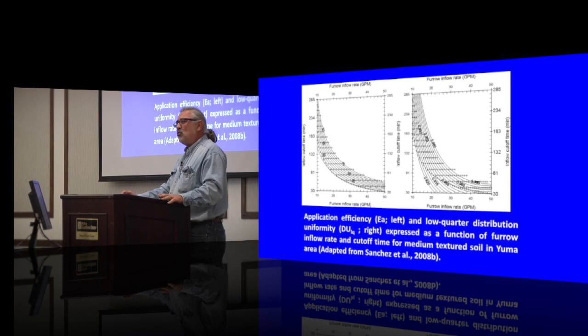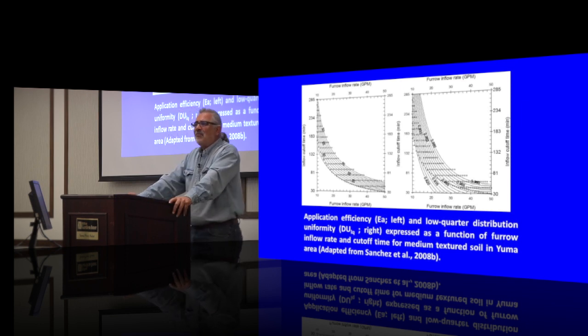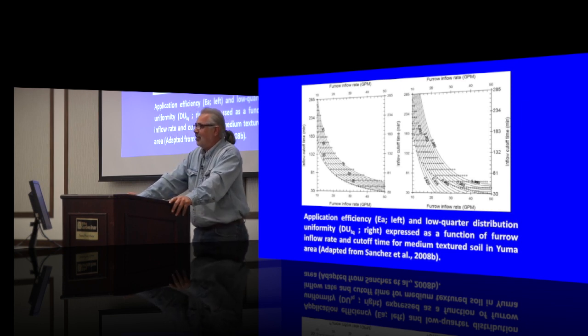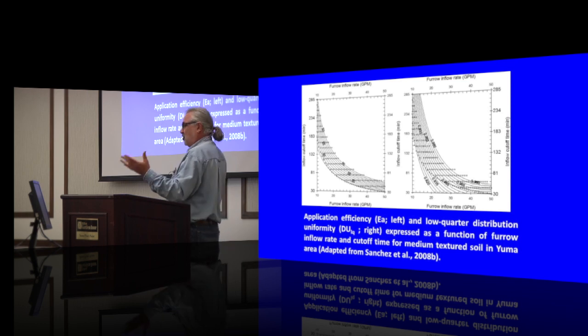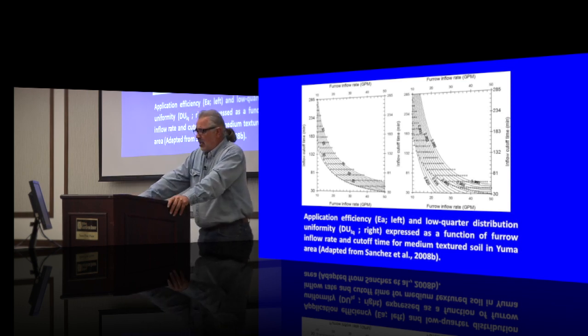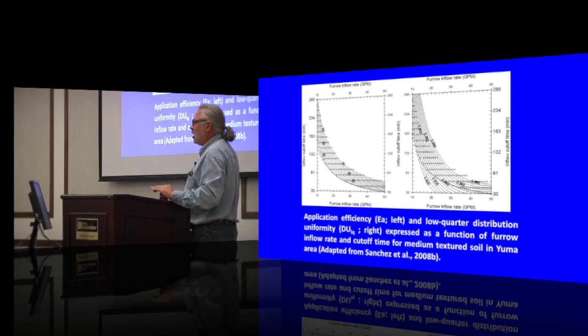But on the other hand, if you use Colorado River water, theoretically you have a leaching requirement of 20%. We do not get a leaching of 20% here. So you can surmise, just from this hydrology data I collected, that within season, we're going to be a slightly salt loading enterprise.